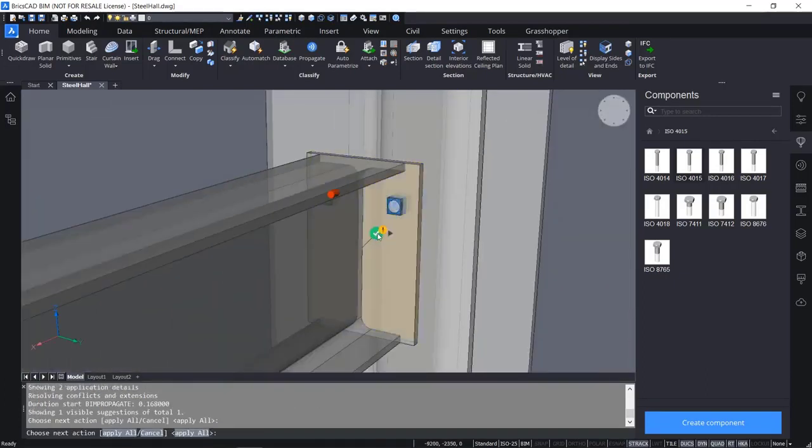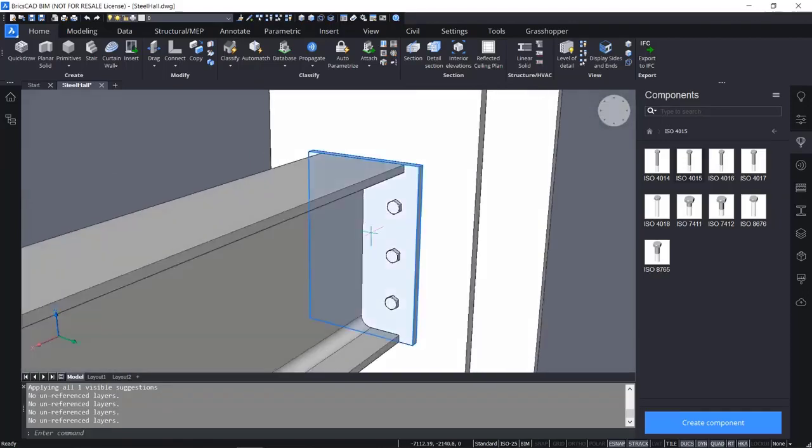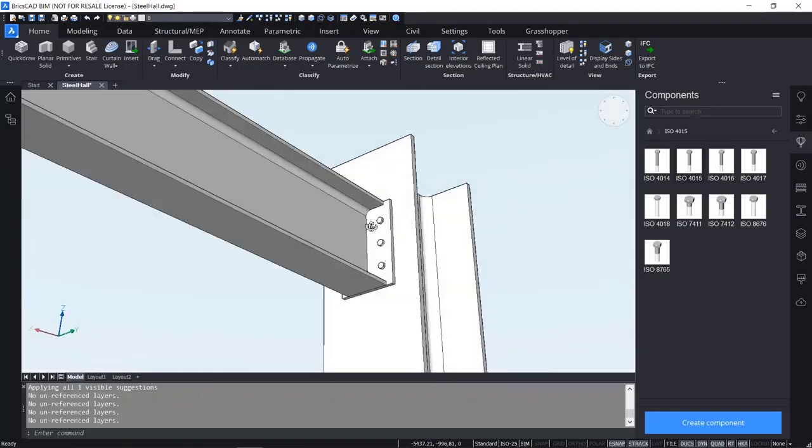It's giving me a question mark. If I turn it in as check mark, I will see already one suggestion based on a similar location, but I want to base it on a grid, an imaginary grid that it creates onto the base solid. And then you can choose, you have standardly a 2x2 grid, and if you add a row, it will add one row. So this is what we want. So click enter to accept, and as you can see, it turns red because it's interfering, but we won't mind for that just now. So click enter to accept, and you have this nicely bolted plate in place.